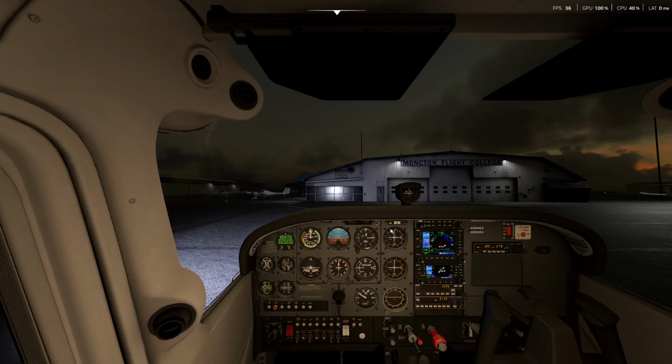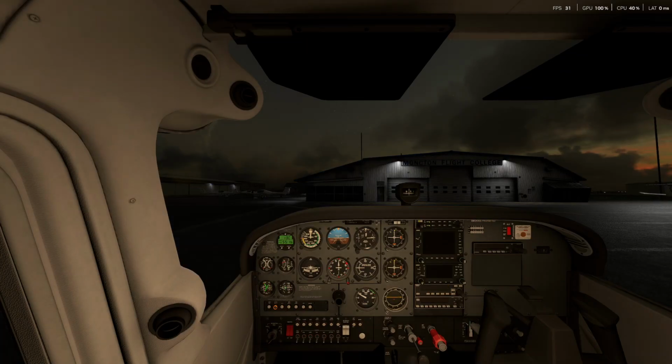Now radios, we'll go ahead and turn those off. Navigation's off. Transponder and ADF. All other electrical equipment is off. Avionics is coming off. Switches are all off. Throttle's down. We'll check idle.